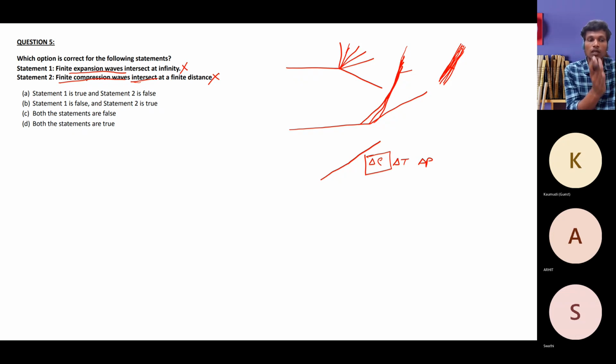They create a thin layer of the shock wave, as the number of compression waves coincide at this particular point. They are just merging, but not overlapping, because every finite wave creates some change in the fluid property.